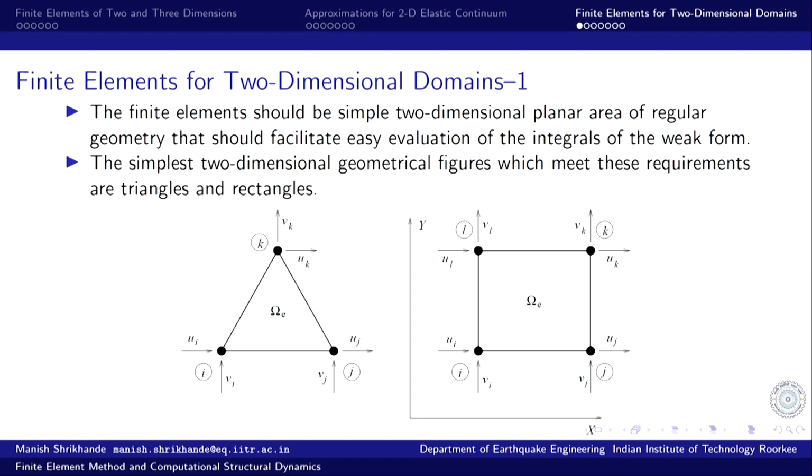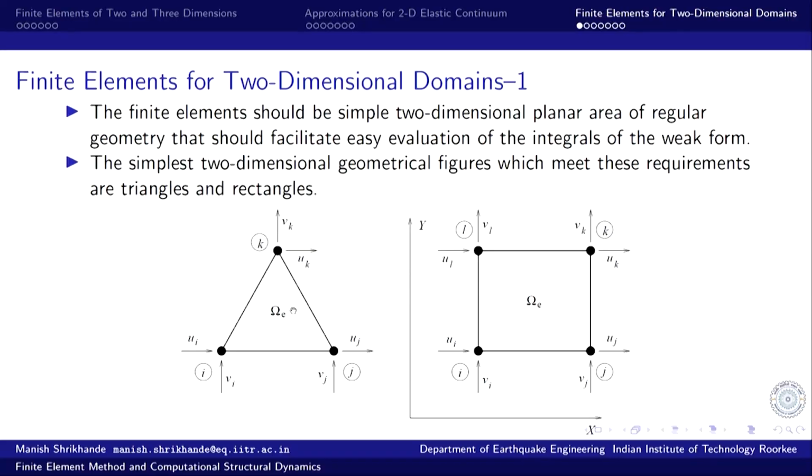So, the nodal values of the primary variable, we do not know what these values are. What is done is this: because the statement of residual is defined over this individual domain, we need to find out the variation of the u displacement in the x direction and the variation of the v displacement in the y direction within this element domain.